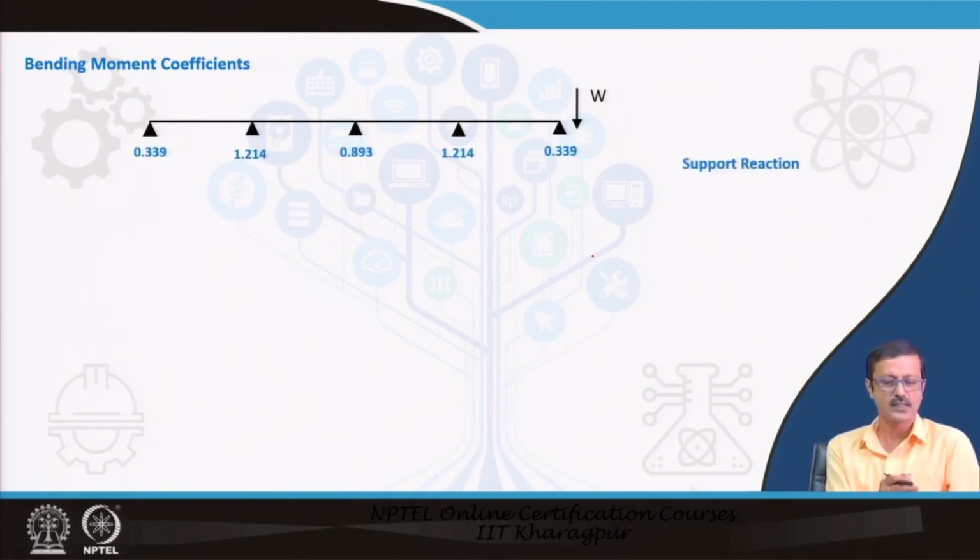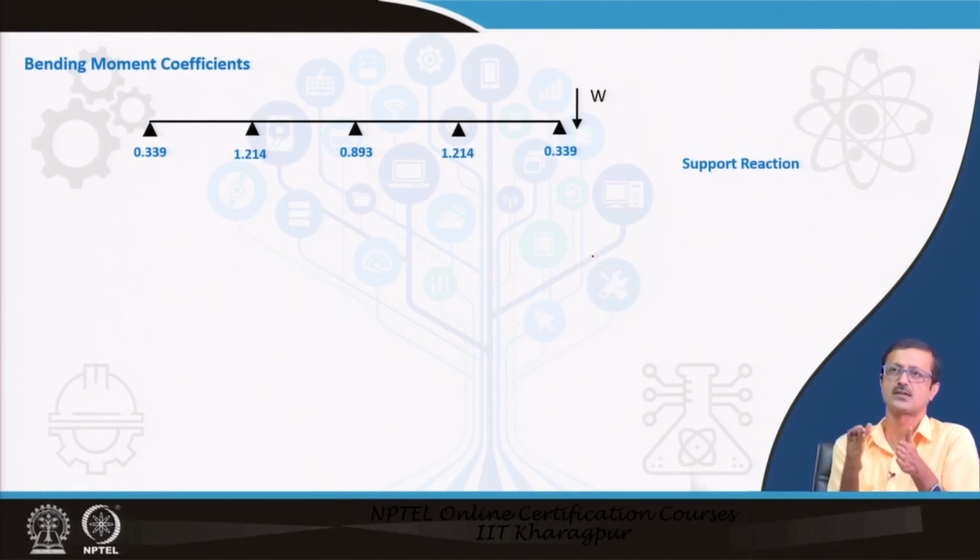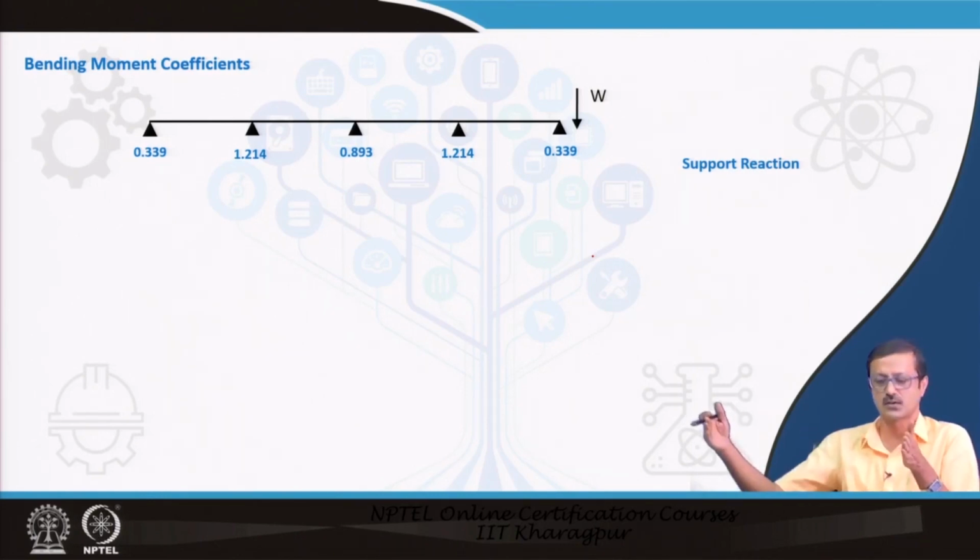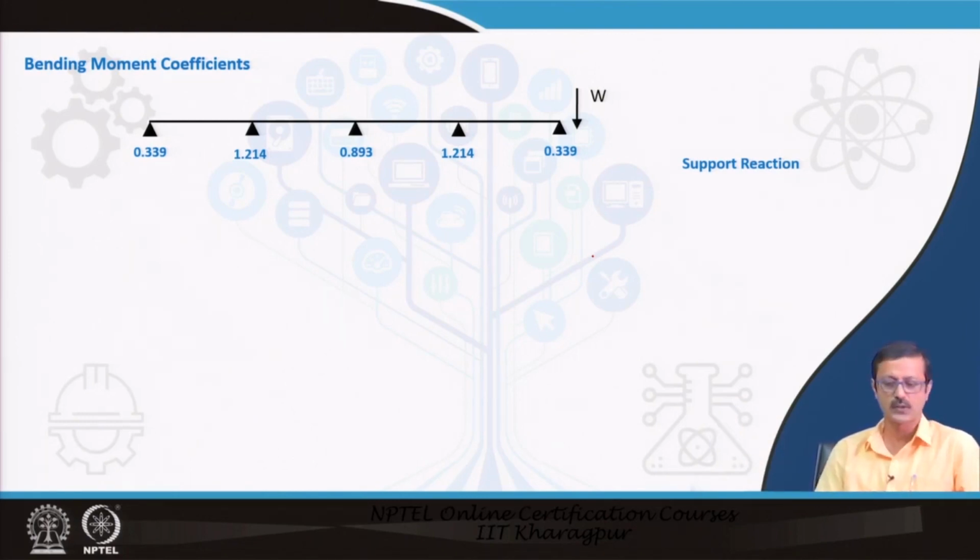For a continuous beam which is simply supported at both ends, having all spans equal and having equal amount of loading, which generally comes in a building like a hostel, that is hostel rooms, or maybe hotels, or maybe some shopping arcade, those kinds of regular interval columns, in that case we can go with this kind of coefficient method also. Those are available in the books. How to use that coefficient I will tell you.